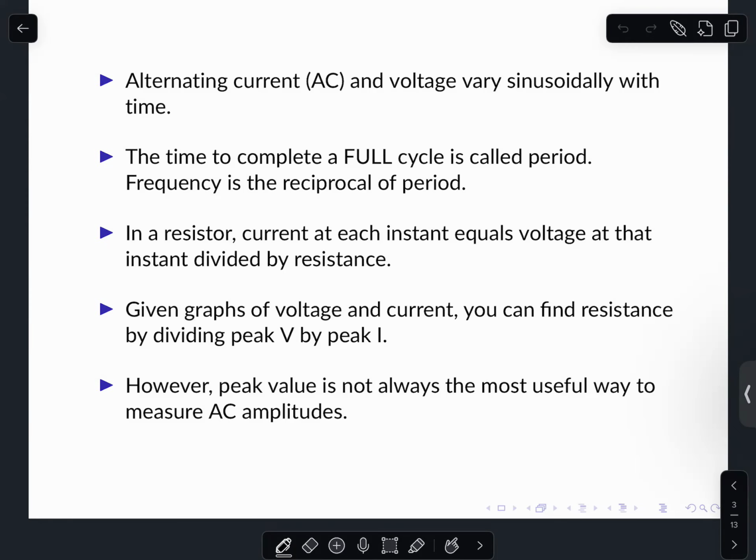The way we practically use this is AC is talking about the form of electricity, and I can talk about what property, the current or the voltage or whatever, about that electricity. So I will say AC voltage, AC current, even though it is silly. Previously, everything we've dealt with heretofore has been DC, and I think I probably mentioned the phrase DC current before, direct current, which is silly. Terminology aside, AC is a signal, a power supply, a voltage that varies like a sine wave.